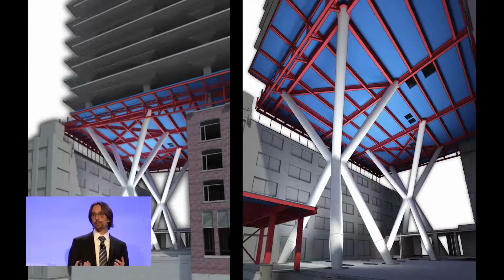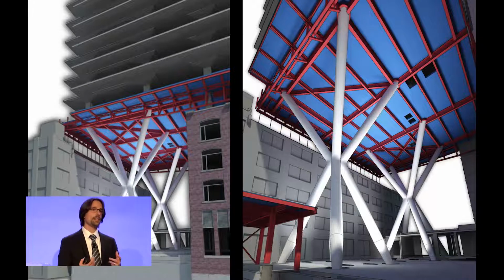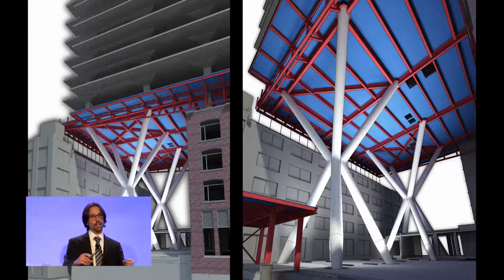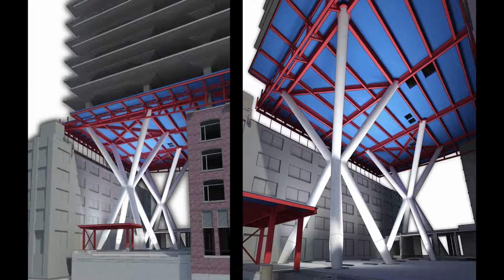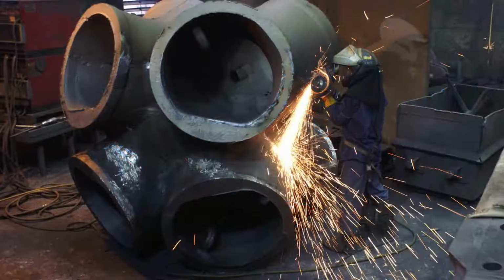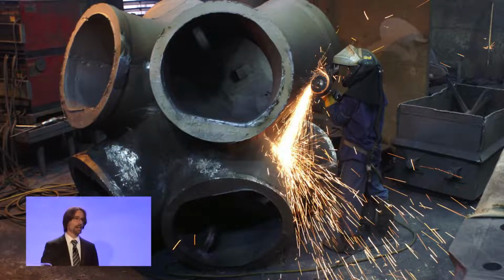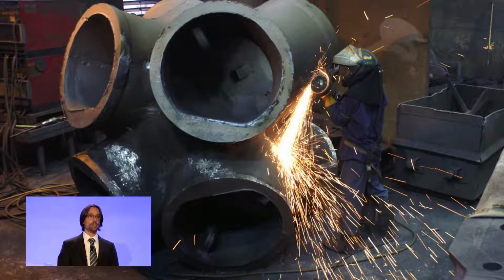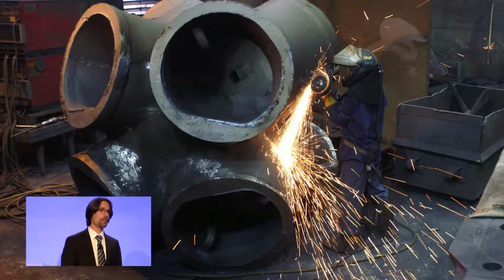But the exterior shaping is really driven by the aesthetic that the architect was after, to try and make it look like the legs were vertically continuous. That was the aesthetic that they wanted. They wanted basically 4 legs that looked vertically continuous. And you can kind of see that in this Revit model that now includes the cast node. And just to give you a sense of the scale of this connection, this particular casting was 32,000 pounds. The diameter on those legs is, I believe, 40 inches and 2-inch wall thickness. Very, very big structure, but very important from an architectural perspective for this design.